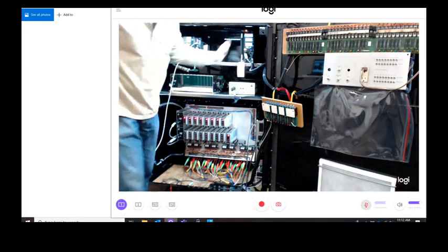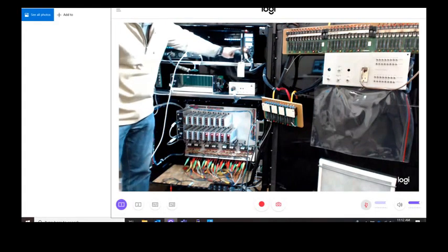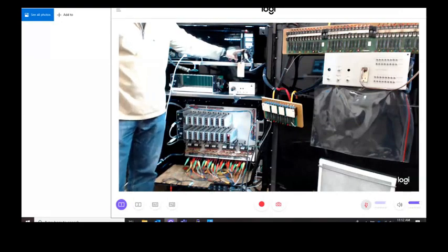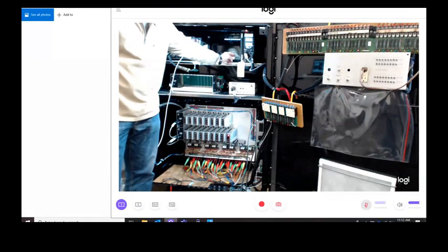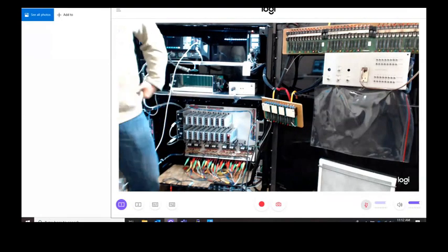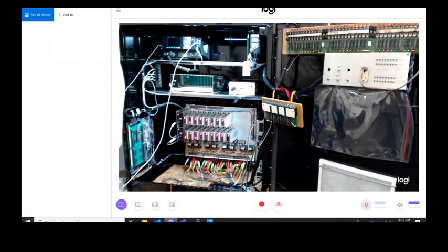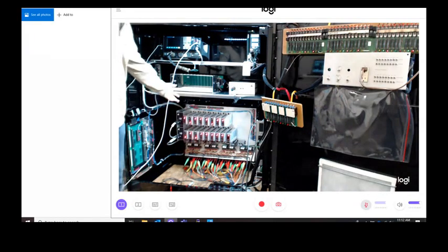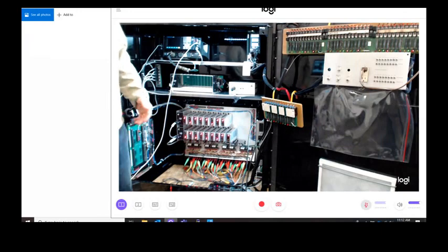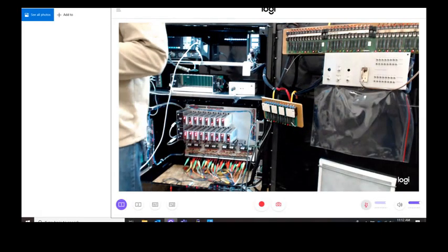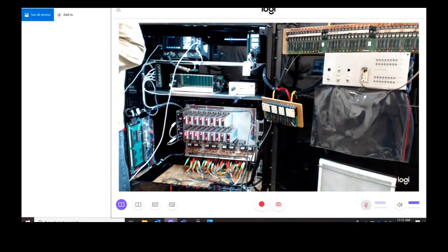Okay. So as soon as I plugged it on, I know it's kind of blurry, but you can see the flash going back on. So that means I'm reestablishing communication. And you'll see that my signals came back on. So now we're up and running again. So that was an example of a port 1 fail on the MMU.